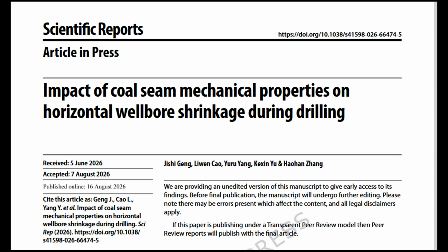Equation 4 introduces a dimensionless normalization that scales the stresses by the elastic modulus and the cohesive strength. This normalization simplifies the mathematics and allows the yield criterion and subsequent equations to be written in a compact, dimensionless form. Equation 5 is the yield surface expression after normalization. It says that, in the plastic zone, the dimensionless tangential stress and radial stress must satisfy a linear relationship fixed by the friction angle, essentially a straight line in stress space that defines the boundary between elastic and plastic behavior.